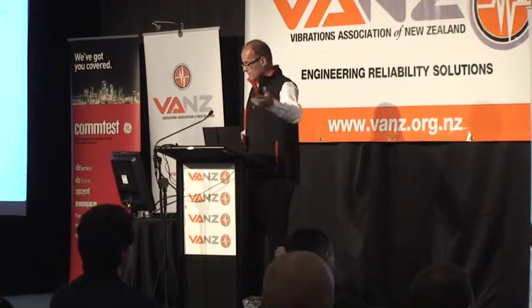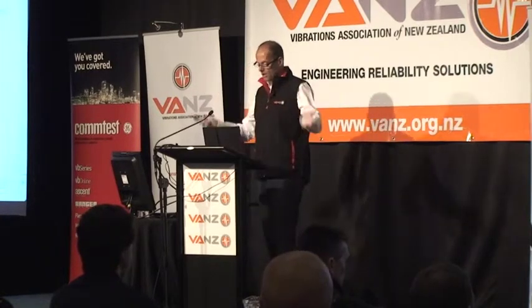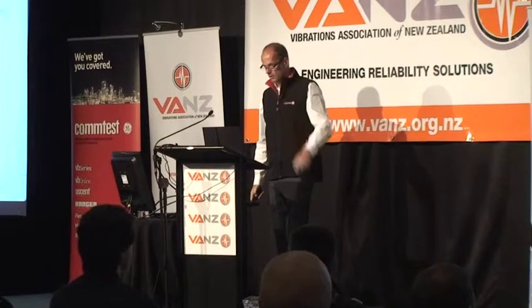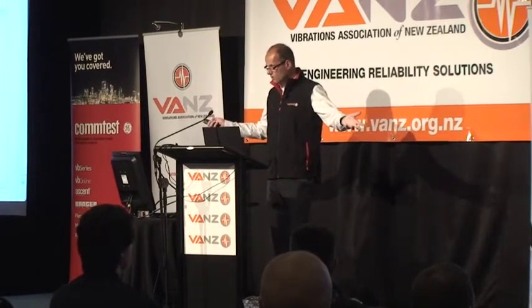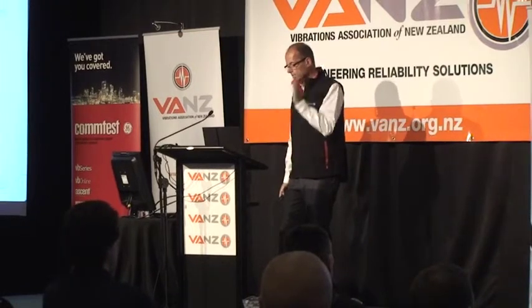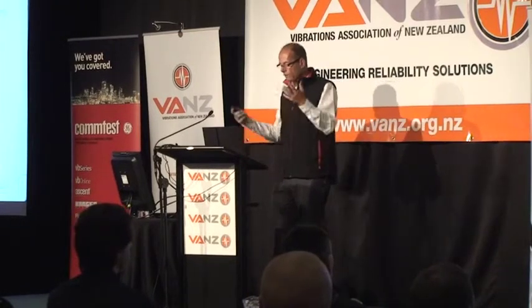We can see it in our time waveform, we can see it in our spectrum, we know exactly what's going on. Same as if the rolling element itself is damaged. And of course we might have a combination of all of these, but if you look closely at these animations, you can see that that is a different rate or frequency to that.